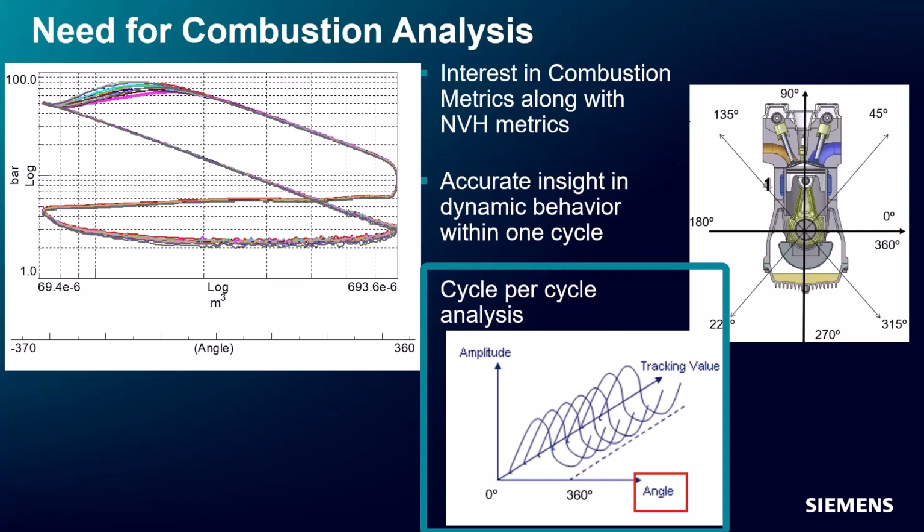The other thing is also sometimes you will see, when the engine is going through combustion, that there can be variation from cycle to cycle. So to really understand how the performance is changing from cycle to cycle and what its effects are on the general vibration and acoustic behavior, you really need to look at even the noise on a cycle by cycle basis. That will give you some valuable insight into the effectiveness of certain combustion schemes and will help you better tune the engine for finding a sweet spot for combustion metrics as well as the NVH.